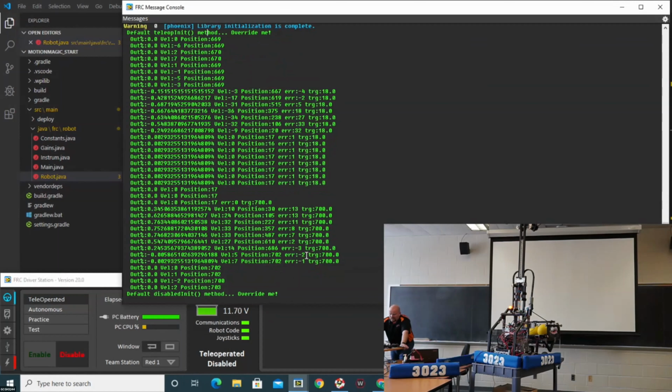If we want to start really dialing this in, if we want accurate position, that's when we're going to start using the D and the I terms. The D term holds back on the horses a little bit so we don't overshoot. And the I term is that if we need a little extra boost as we get there, we can turn on the I. The I is an accumulative value, and that's why we want to make sure we have our zone, so it only is being applied when we hit our set point.